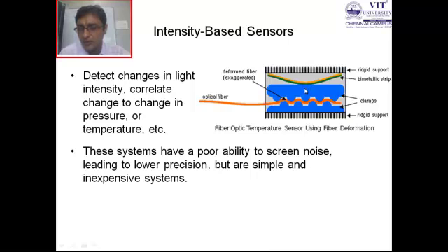Now here you see the waveform will initially have the maximum intensity of power when you don't have any pressure being exerted, and the minimum of it when the whole of it is being exerted on deformer 1. That is nothing but you converting the pressure into its electrical equivalent using the optical fiber cable.